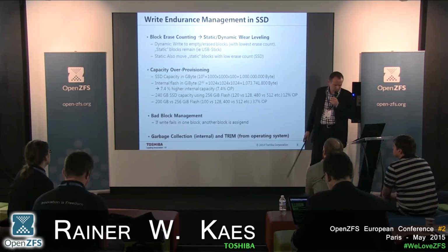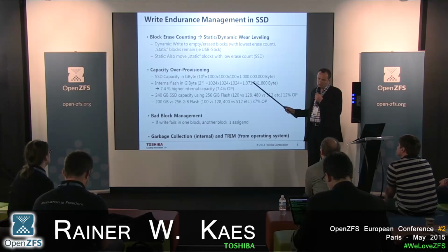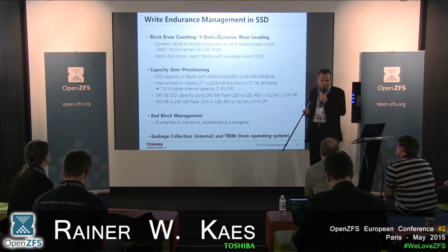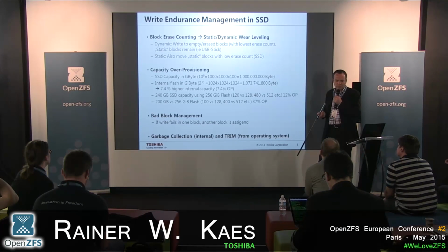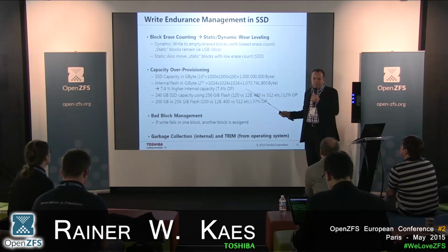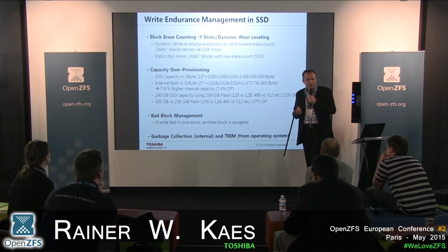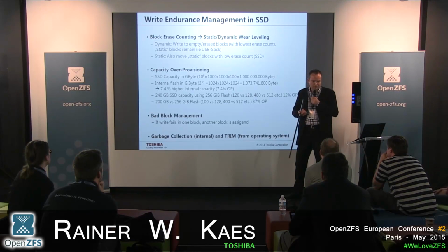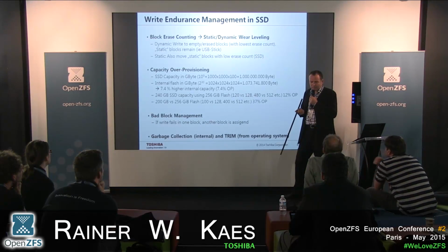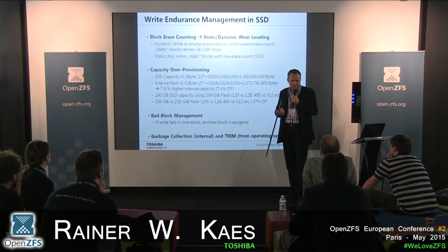The over-provisioning also is important for the consistent write speed of the SSD. I said earlier, to erase, we need to charge the 10 volt, and we need, first of all, to generate the 10 volt, and we need to apply the 10 volt for some time in order to squeeze out all the charge there. And this takes time. So the erase cycle of an SSD takes a very long time. And if a full stream of data is coming into an SSD and there are no free cells and the SSD has to start erasing cells, then the SSD drops in performance quite drastically. The only way to do something against this is to have spare areas available where there can't be any user data, so that the SSD can do some offline pre-erasing.